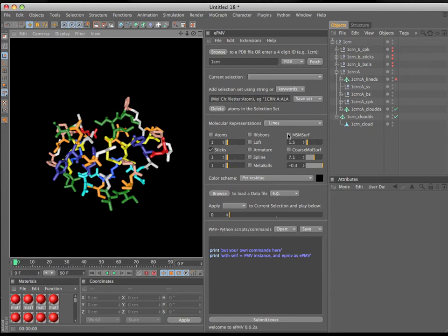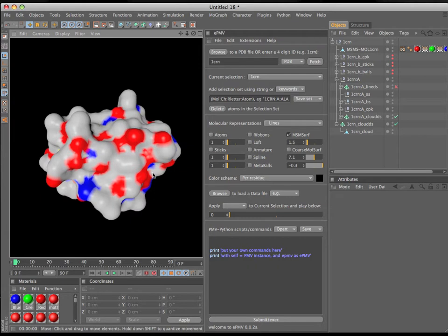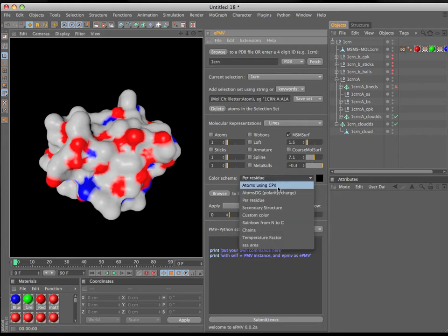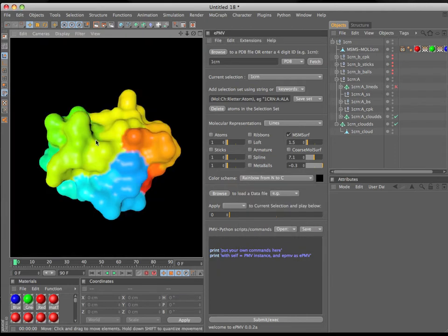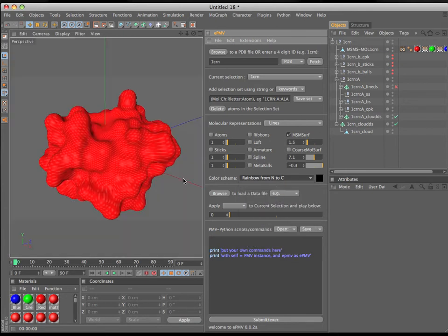We can generate molecular surfaces, and this is unique. Typically if you import a VRML file exported from a molecular graphics viewer into a hosting software application, these software packages aren't designed to view the vertex coloring scheme that you see in your molecular graphics viewer, and we've set up a workaround for that that allows you to get these color representations during your render time exactly as you would expect from your molecular graphics viewer.